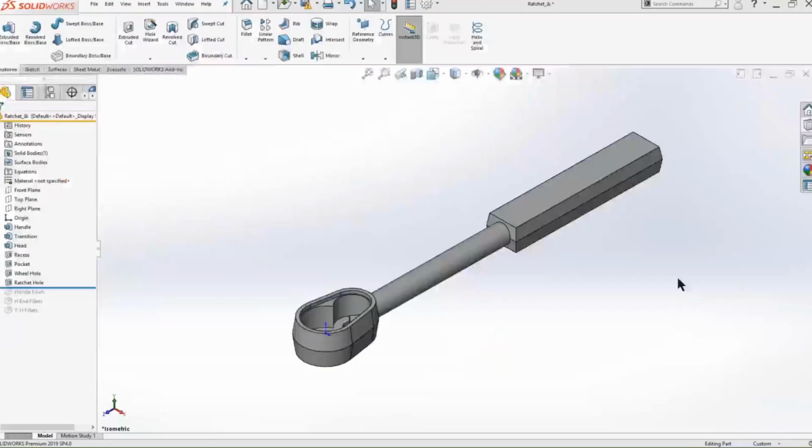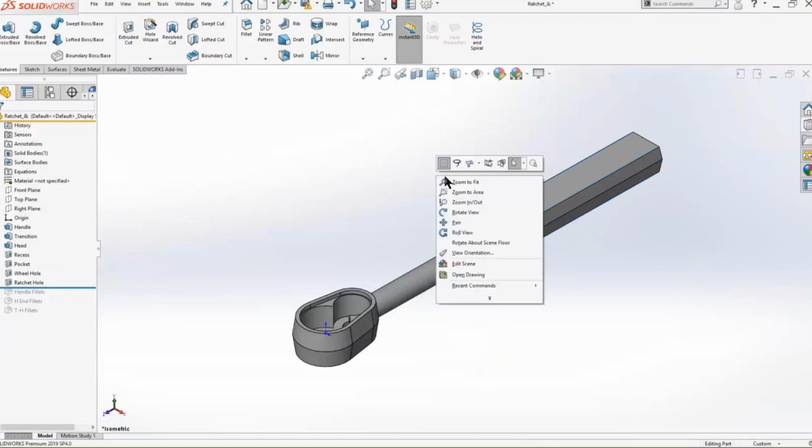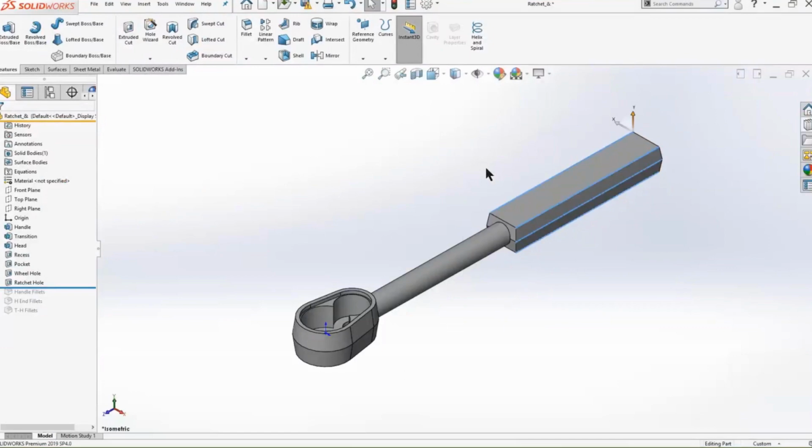Another quite useful item is the ability to use the previous selection. So maybe you're working on a part such as we have on screen here. I know I've done this. I've selected a number of edges to maybe fillet, and I accidentally click in empty space, which of course clears the selection. Well, in the right-click menu, you can see a previous selection. So SOLIDWORKS remembers that one step prior. So you can always get to it, and it's in that right-click menu.